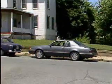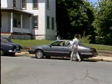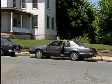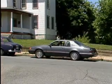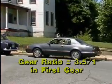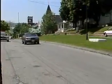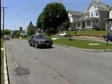Gears are selected for particular jobs based on what the requirements are for either speed, torque, or both at the output of a gear set. For example, the next time you're driving to work, imagine what it would be like if you had to travel the entire distance in first gear. The gear ratio in this car is about 3.5 to 1 in first gear. You'd certainly have plenty of torque, but your top speed would be pretty slow.